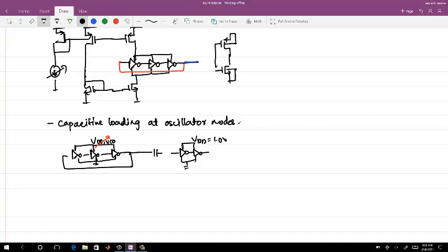Right now, who will give the biasing for this with the AC coupling? The way to do it is I can use a resistor. So you have a coupling cap with a resistor, followed by this. Now this is C AC coupling, and this is C P parasitic.